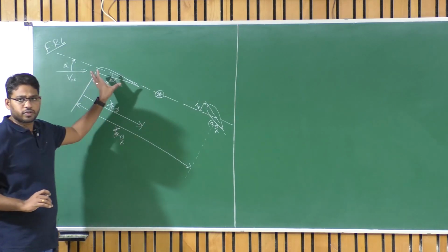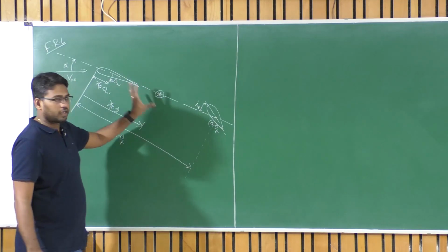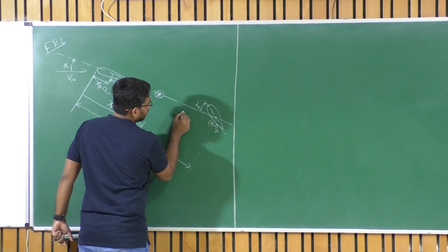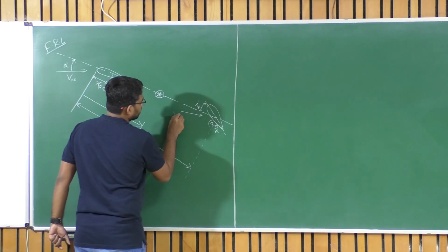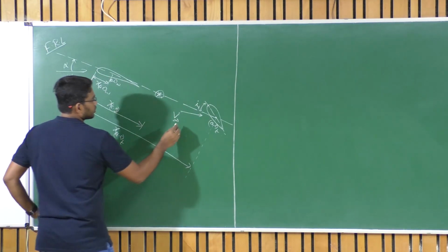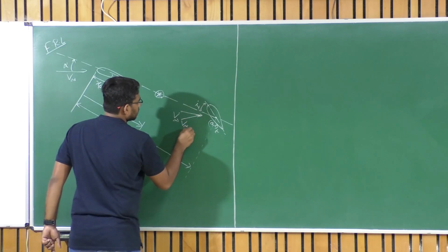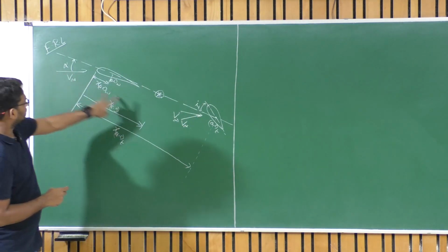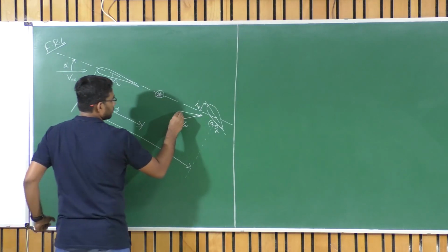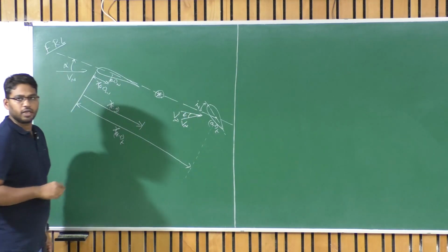Now due to the downwash of the wing, because of the presence of the wing there is a downwash near the tail, right? That's because of the wing. So due to this, the resultant flow will be V infinity prime, which is different compared to that of V infinity here, right? So what the aircraft is facing. The initial or the wing V infinity is parallel to this, right? These two, let's assume these two are parallel, and then there is a modified flow at the tail due to the downwash, which is the effect of epsilon, right?